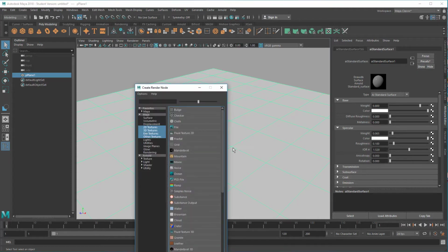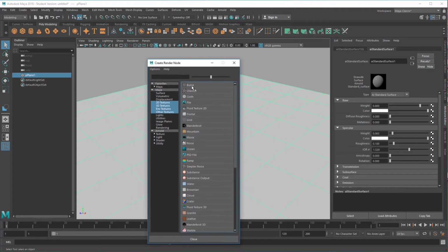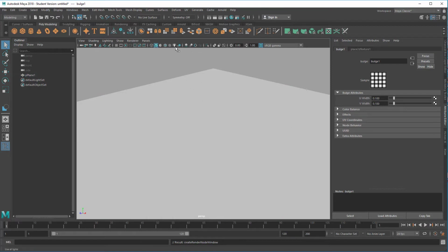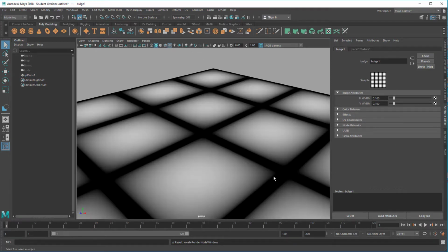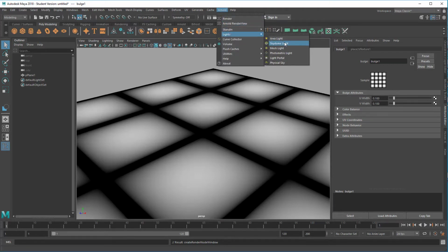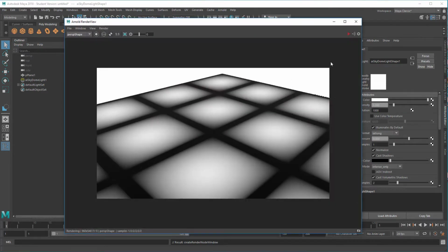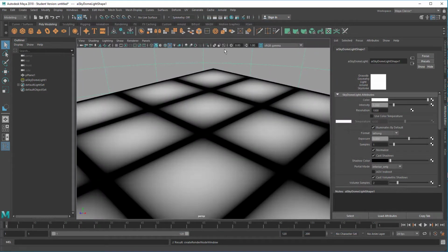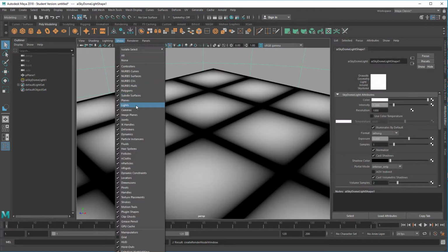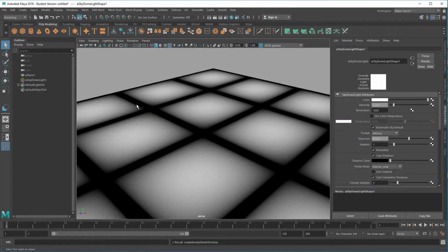We go to the checkerboard icon here and we choose a bulge texture, which we see when we click here. So we need a light now, the Skydome light, which sits here, and if we render it, this is what we get. Quite nice. Since we don't want to pick the light inadvertently, let's uncheck it here. All lights won't be visible here, but they're still in the scene.